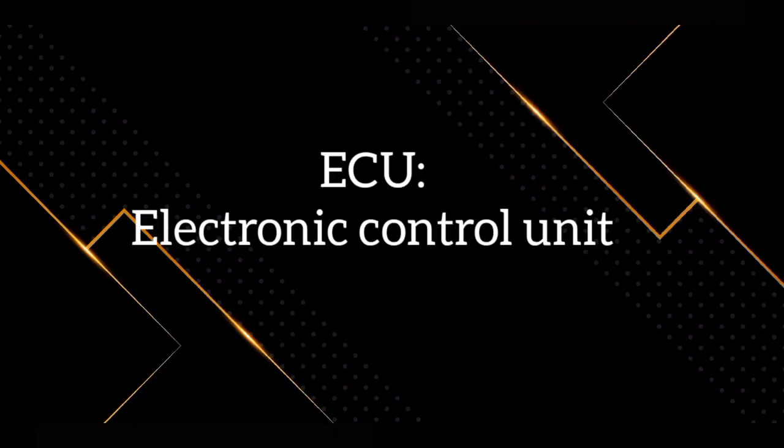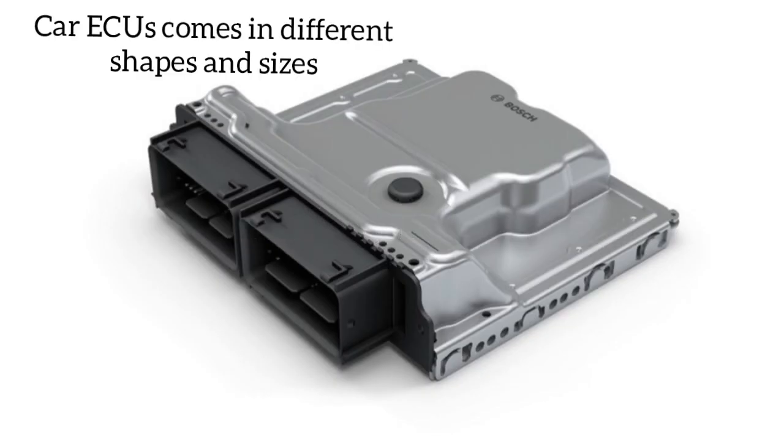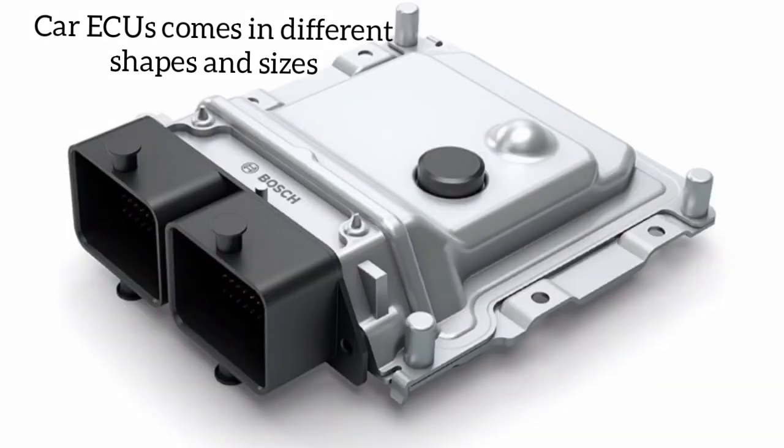Next up, we have the ECU, and this is popularly known among tuners and those people that are into tuning their cars. So it stands for electronic control unit, and this is a device that regulates all aspects of engine variable controls. Like, it regulates the amount of fuel that goes into the engine cylinder, it regulates the spark plug timings, it regulates the amount of air that goes into the engine, it regulates the emissions, like it regulates everything that makes the engine make as much power and run as smooth as possible.